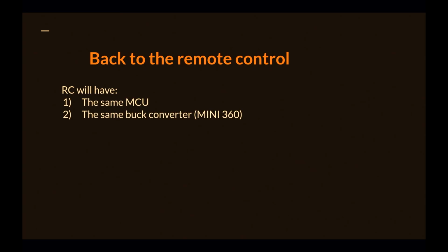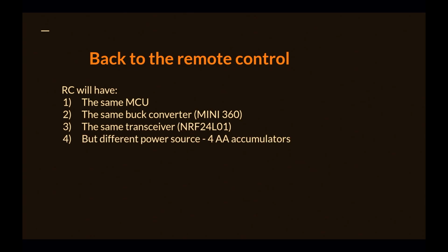So now let's go back to the remote control. The remote control will have the same microcontroller, the same buck converter, but only one of them, and the same transceiver. We will power it from just 4 AA accumulators. And one more component will be a joystick.